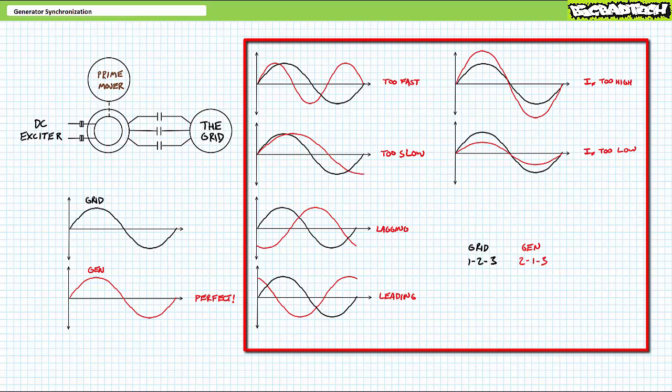Anytime the contactor, essentially a low resistance switch, closes with a voltage differential across it, a massive surge of current can occur. Depending upon the instantaneous voltage values of the generator and grid at the time of closure, sometimes this current surges into the generator and sometimes out of it. All of these scenarios involve potentially high voltage across a low resistance switch at the moment of closure, a sure recipe for a massive surge of current. In summary, different is bad.